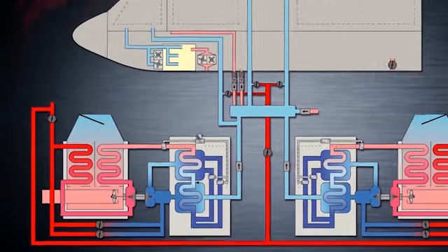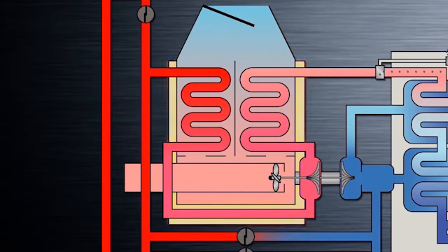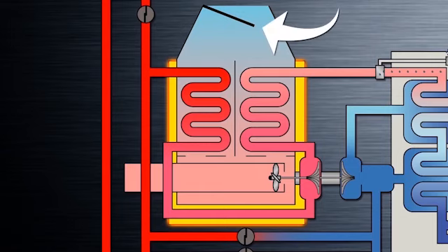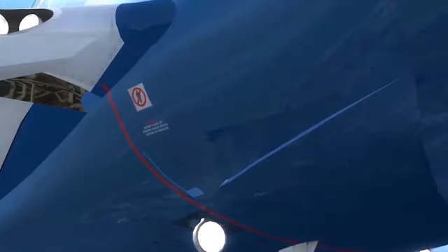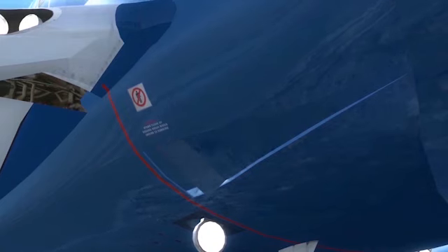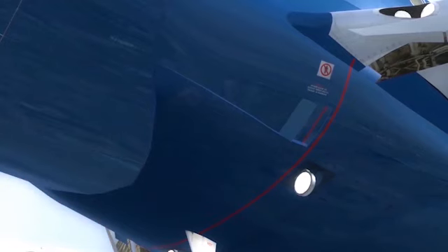After the flow control stage, air passes through a heat exchanger where ram air cools down the bleed air. Ram air is external dynamic air that enters the aircraft through a ram air inlet door. When the aircraft is moving slowly, such as during slow flight, low air density, or ground operations, the ram air inlet door opens to its fully open position to maximize air intake. When this occurs, a ram door full open light illuminates in blue color in the forward overhead panel. Under normal circumstances, the door automatically varies between the open and closed position.